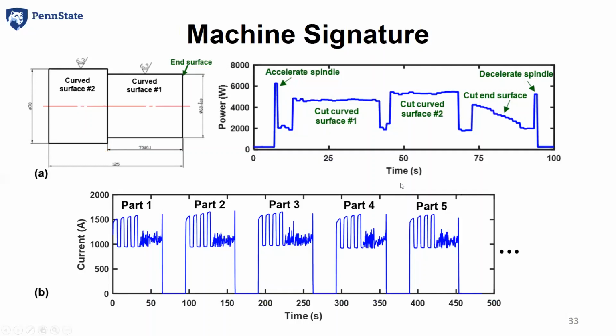Now let's have a look at the welding process. This is the signal we collect from the welding process. So if we weld two parts, we see different kinds of electric current, and we call this flash welding or electric welding. And as we can see, there are some activities over here. There's a huge difference. The amplitude is a little bit different. And those electric currents, those signatures, actually tell a great deal of information about the quality of each part.